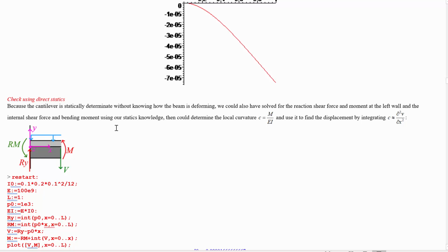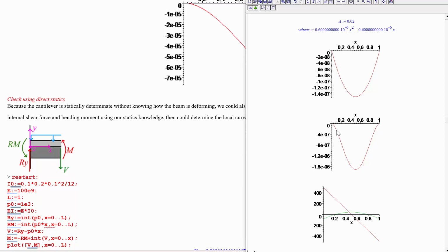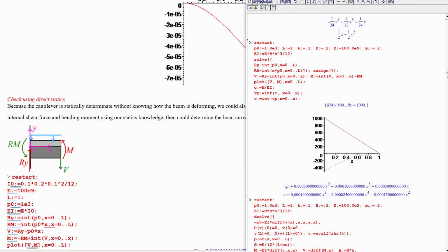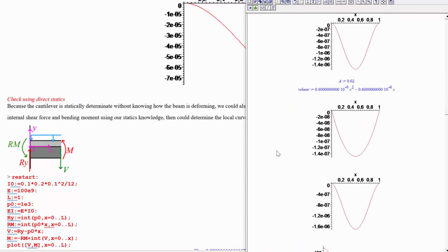So that means we're putting a moment in the direction that RM is showing there to stop it from bending, from sloping down. We're kind of pushing it out at the bottom of the wall to stop it from going into a pin support. Imagine what it would do if it was a pin, and then think about what moment you'd have to apply to stop it from sagging down and doing that pin displacement where it's able to have